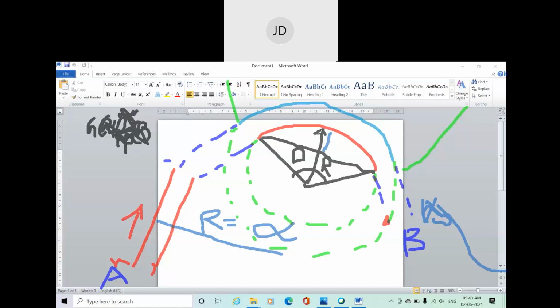What is super elevation? Super elevation is defined as the rise of the outer rail with respect to the inner rail, especially in a curve, this part. So this outer rail is raised some amount with respect to this inner rail to counteract the centrifugal force. We're going to discuss that in coming classes. Anyway, whatever the value of super elevation decided from design, it is not directly provided. It is gradually increased up to this point from the straight path to the circular curve.